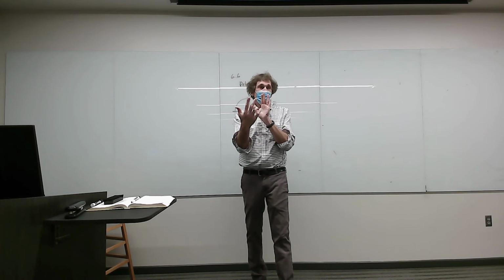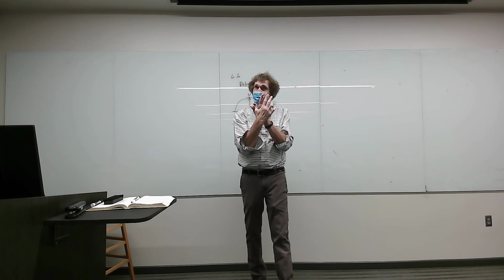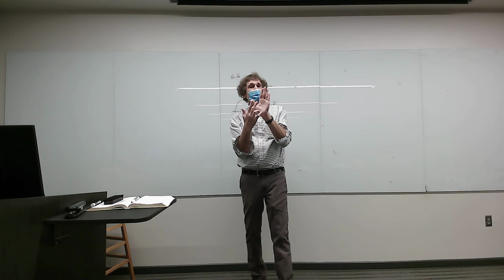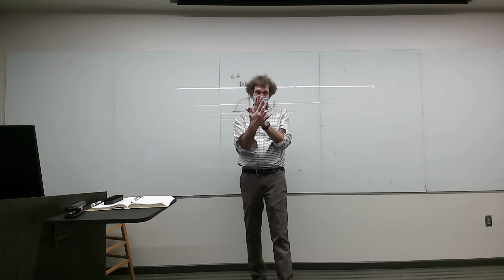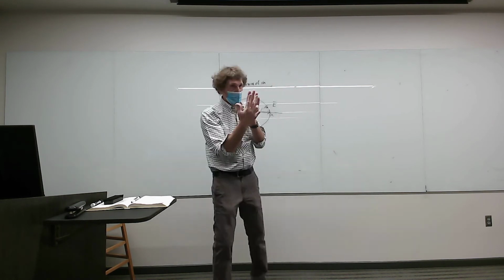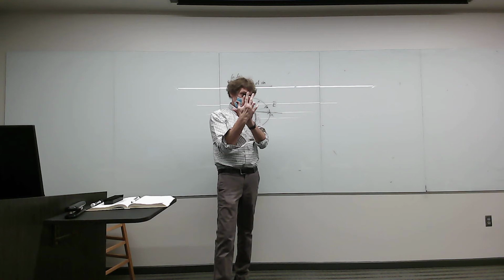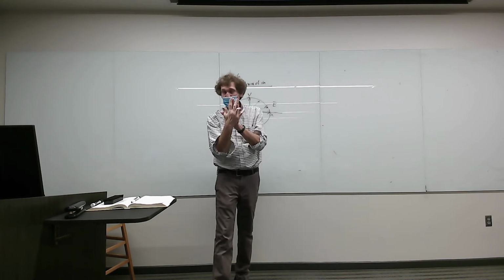If I know they're trying to jam me, for instance, all right? If I send out a right-hand circular polarized wave, they don't really know, well, they could if they're clever, what kind of polarization. But I can discriminate the actual target reflections from other incoming information at that same frequency. Do y'all follow me? Because I can put what's called this polarization filter. There's right-hand and left-hand polarization filters, and I could say only right-hand or left-hand polarization at that frequency would I accept and look at. Everything else I discriminate and get rid of. That's the reason polarization is so important.